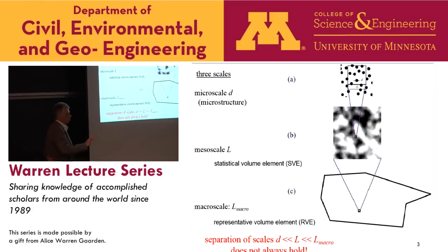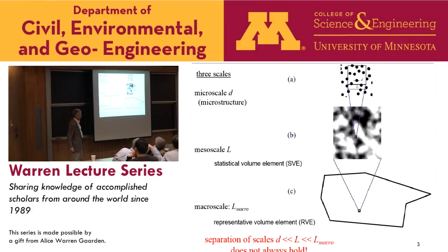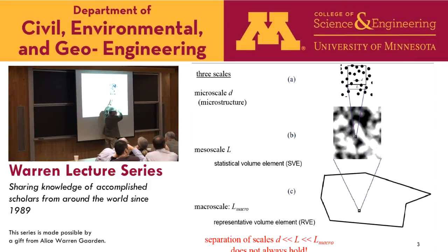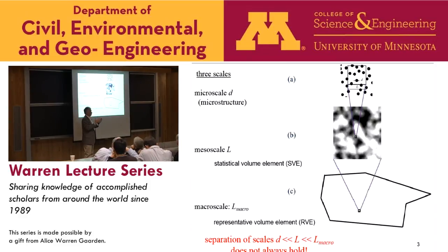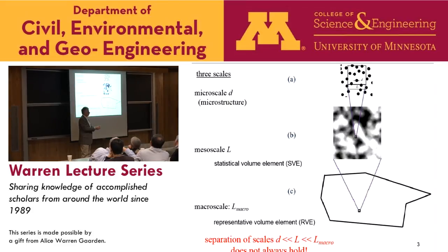So we should always use, I mean, classical continuum mechanics is very nice. Just be careful about what it means when we apply it to some polycrystal with 1,000 grains where the noise is still present on this scale. And we have done some problems. There are two competing trends. One trend is the finite element trend. With finite elements, you want to have a very fine mesh to resolve a homogeneous medium. But if I have a very fine mesh, then the mesh begins to see the microstructural noise. So there's the opposite trend to homogenization.